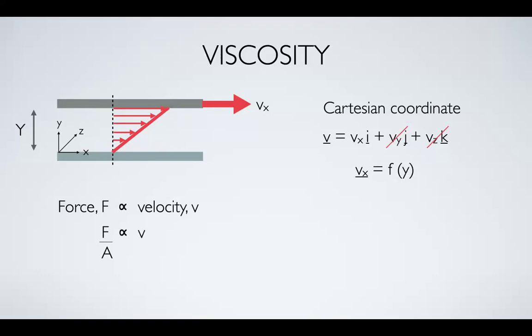And if you consider the gap between the top and the bottom plate, it's going to affect the velocity that is pulling as well. Do you think the smaller gap or larger gap, which one is harder to pull? Smaller, yeah. Because when you have a very small gap between two plates, the liquid behaves like a resistance between both plates. So it's harder to pull.